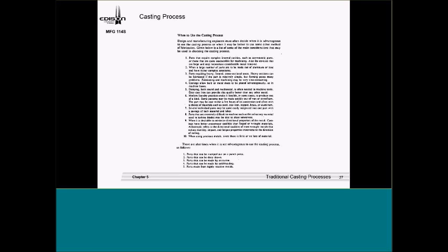Of course, in fabrication, you still have some machining, but not quite as vast, unless you have internal cavities. So I talk about, again, the lead time, the cost, fabrication, the lead time, the cost, if you have post-heating or stress relieving, et cetera, so on and so forth. So they get a comparison of really when it's advantageous to use one or the other process.